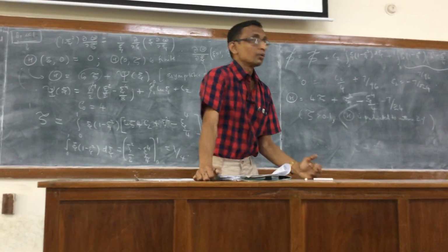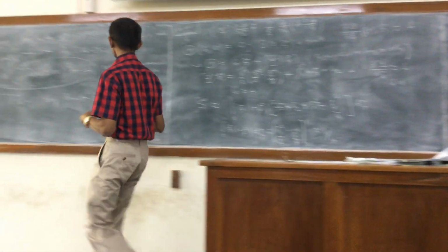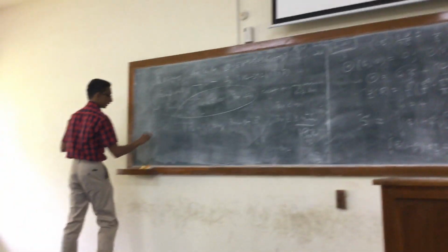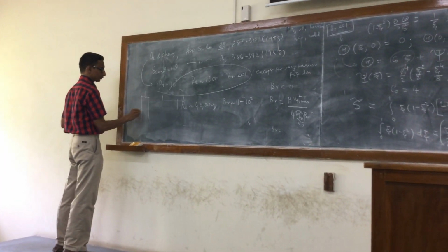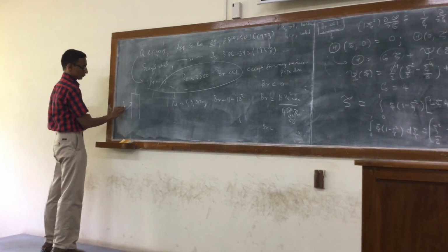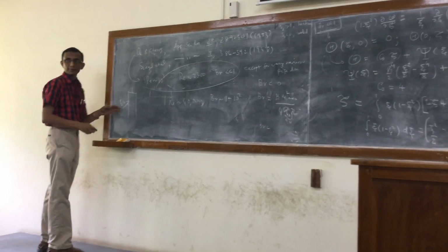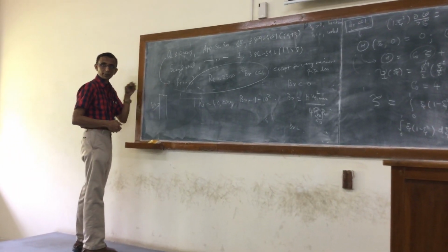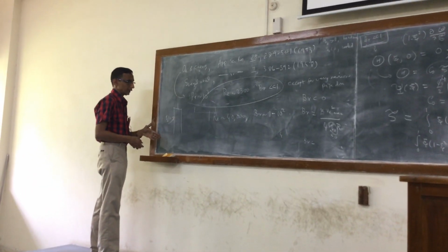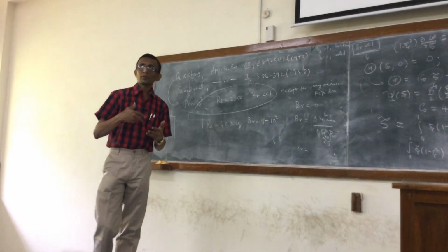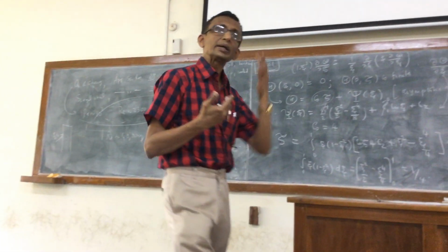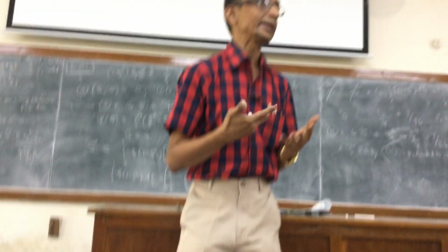So what happens is, for instance, considering the fluid flowing down, and let's consider the case where it is being heated, so that means Q0 is greater than 0, so the arrow indicates that heat is input to the fluid and it's being heated. You can see the viscous dissipation is also going to cause a heating effect.